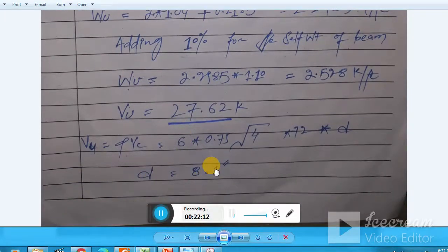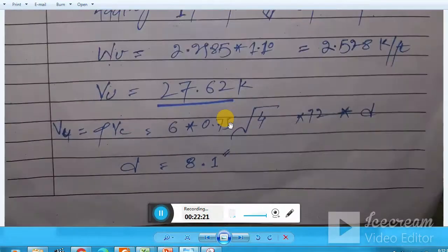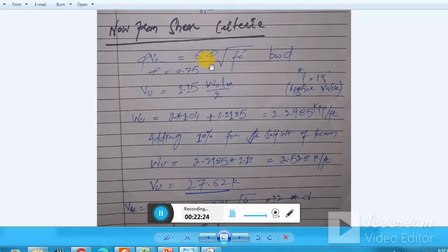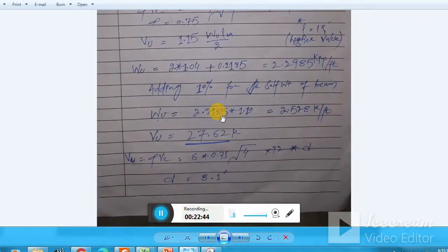So this suggests that we have to control shear, because if the shear value becomes more than that 6 phi or 8 phi, I think so, then we have to revise the beam design. We have to revise because practically it is impossible if the shear amount is more. So we try to minimize the shear to less than this value. This is very important, and this is the beauty.